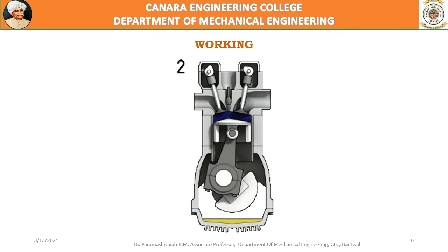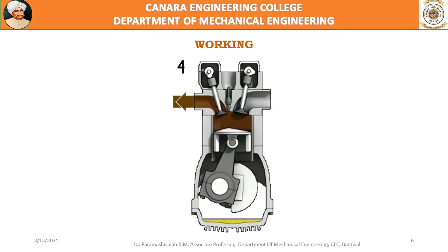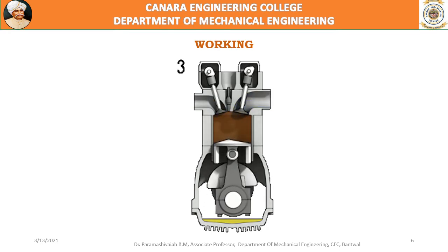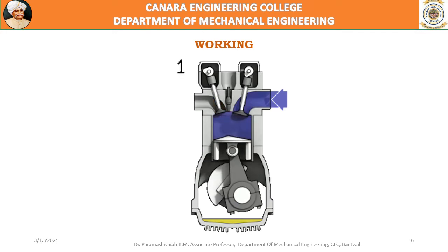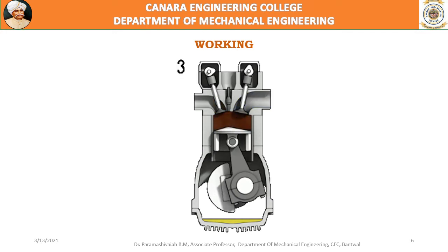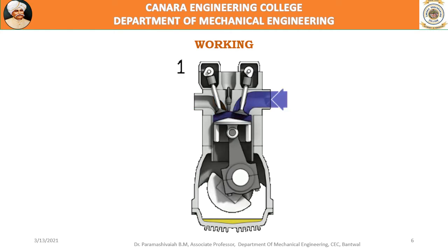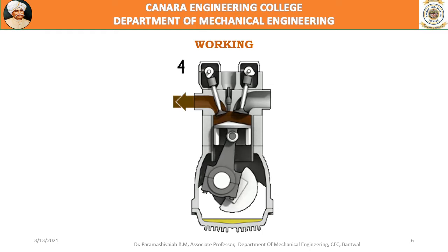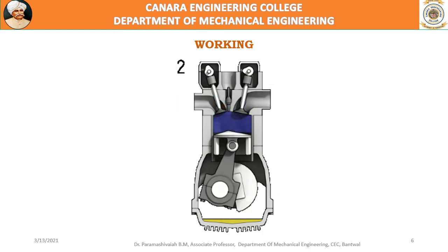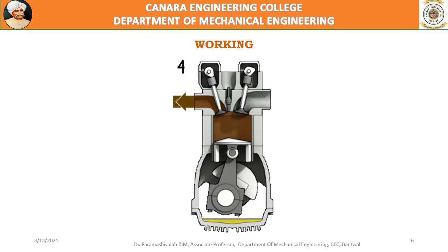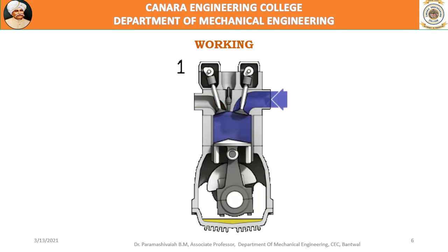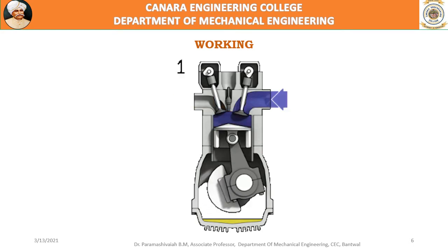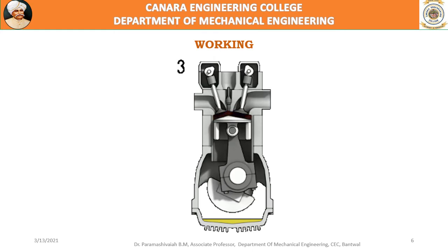Okay, this animated video represents the working of a four-stroke engine, four-stroke internal combustion engines. It is called four-stroke because to complete one complete cycle, it makes four strokes. So during these four strokes, it rotates the crank two rotations. So one complete cycle, four strokes, two complete rotations of the crank or wheel. So such engines are called four-stroke engines.